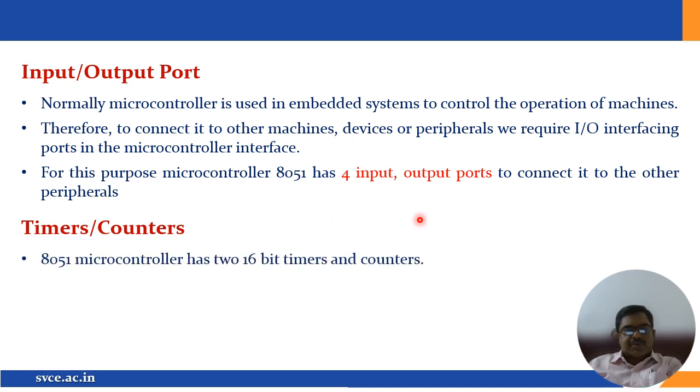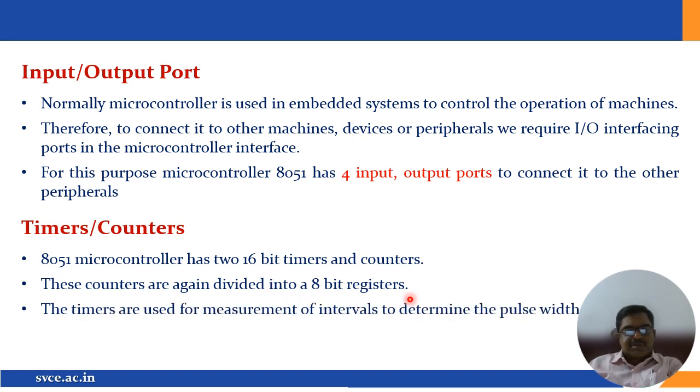Timers and counters: the 8051 microcontroller has 16-bit timers and counters. These counters are again divided into 8-bit registers. The timers are used for measurement of intervals to determine the pulse width of the signal.